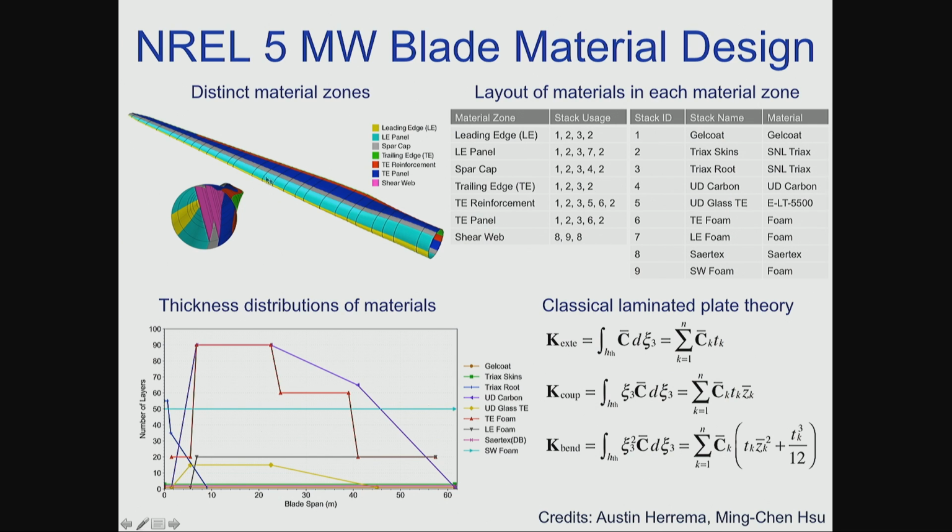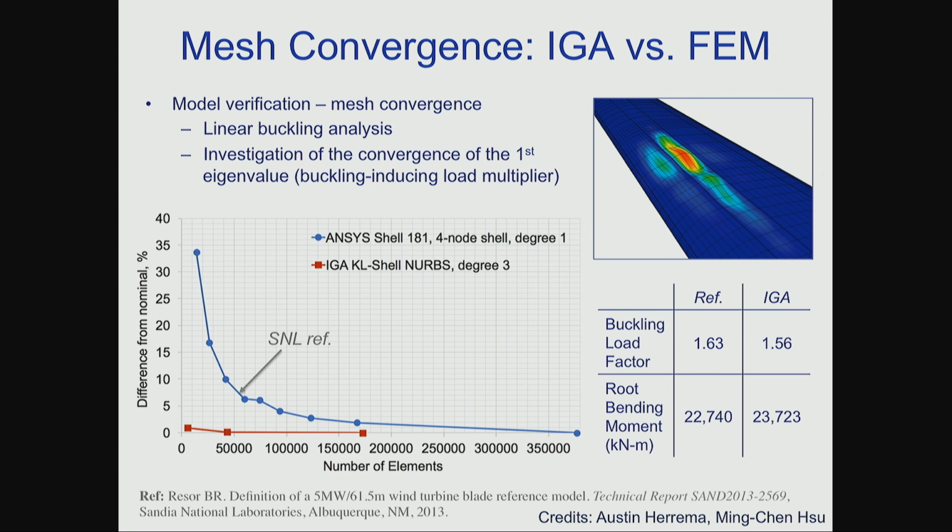This is complicated. This is a real structure. It has many different materials, and all of the materials are stacked in composite layers. So this is the real design. It's done now. It's complicated. That's your analysis file. You compute with that in isogeometric analysis. And the design code gives you the critical buckling mode basically to engineering accuracy without any further refinement. If you refine, you can refine to your heart's content. Nothing's changing.